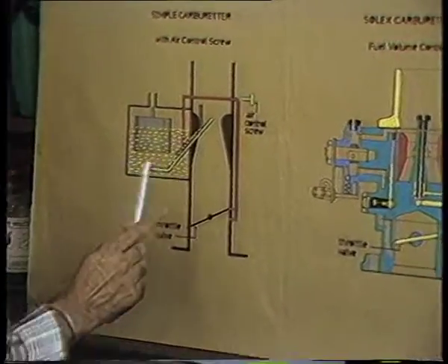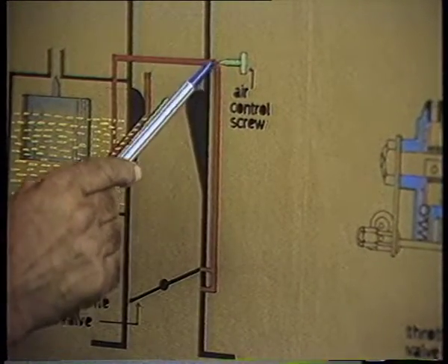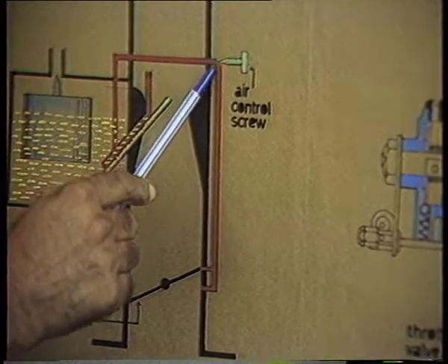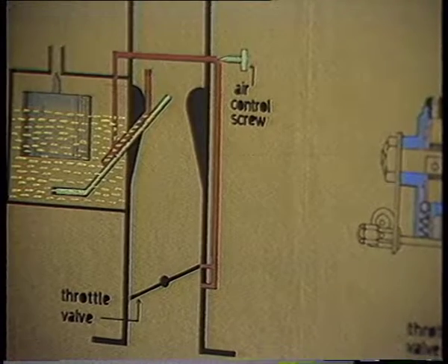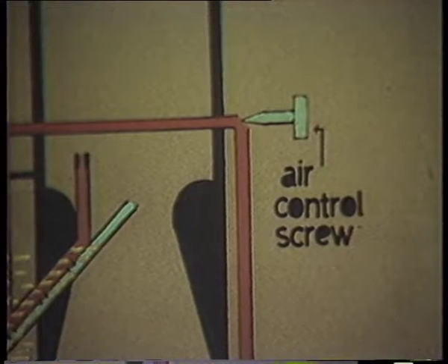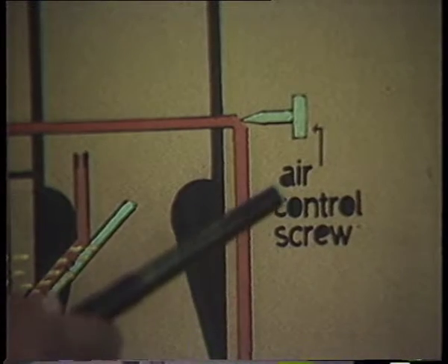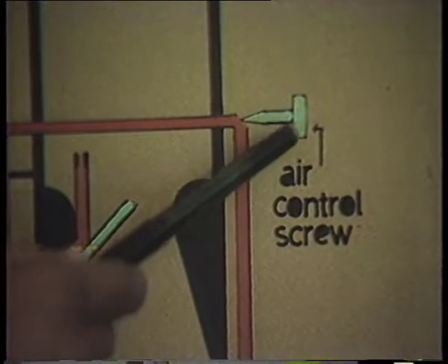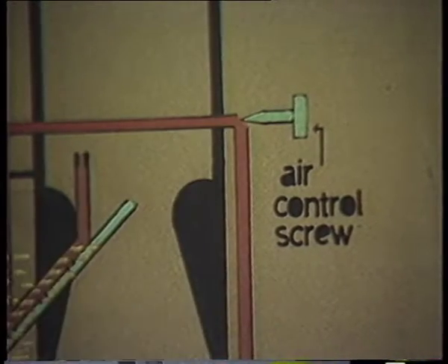An air regulating screw adjusts the amount of air permitted to pass the cone of the screw into the channel connecting the idle jet and the idle discharge hole. For a richer mixture, the screw is turned clockwise, bringing the cone of the screw nearer to its seating. Conversely, turning the screw anti-clockwise results in a weaker mixture.